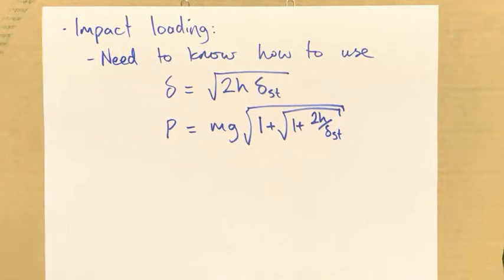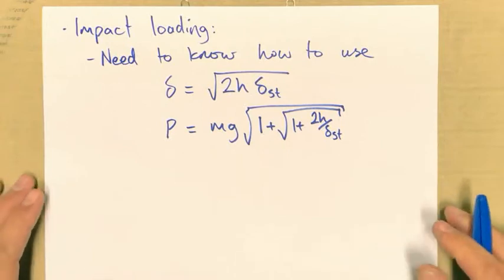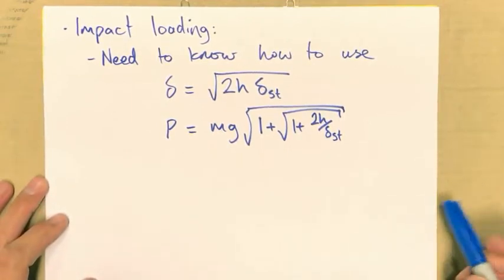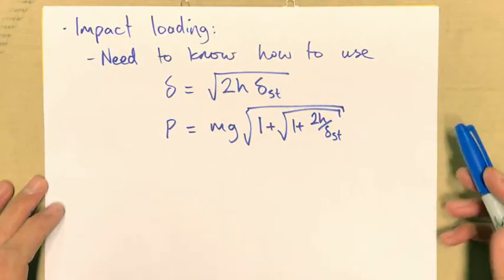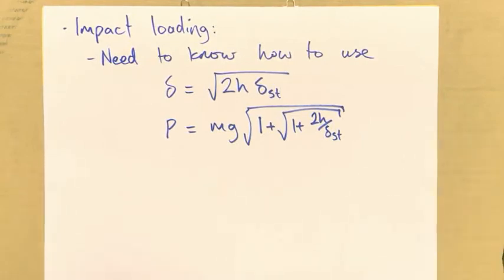And you should know, of course, that the impact load is determined by equating the strain energy in the solid that is being hit with either the potential energy of a mass hitting the solid or the kinetic energy if you knew the velocity of an object hitting the solid. You will find in previous exams that I've required you to be able to equate strain energy in a solid to the incoming energy of a moving object.